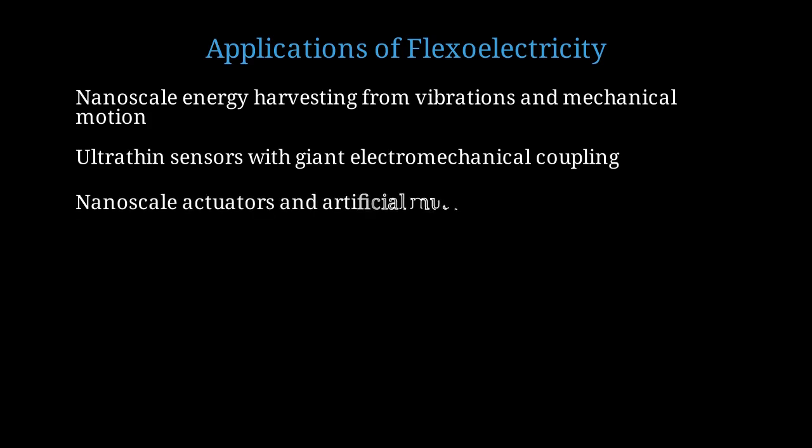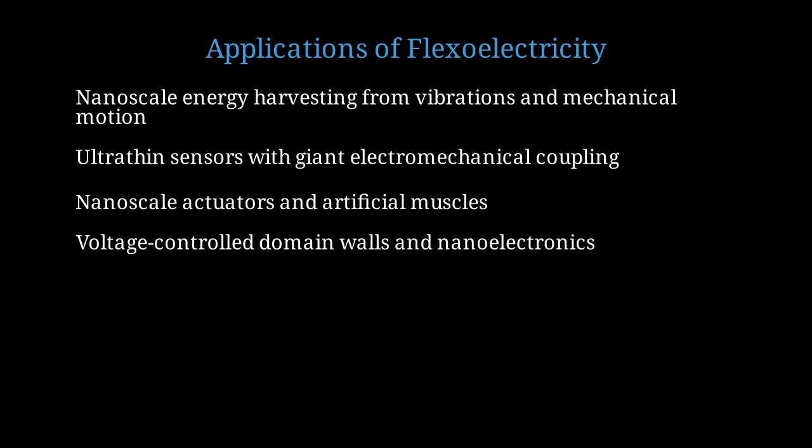Converse flexoelectricity, where electric fields generate strain gradients, enables nanoscale actuators and artificial muscle applications with precise control. Flexoelectric fields can manipulate domain walls and electronic properties at nanoscale interfaces, opening paths for novel nanoelectronic devices.